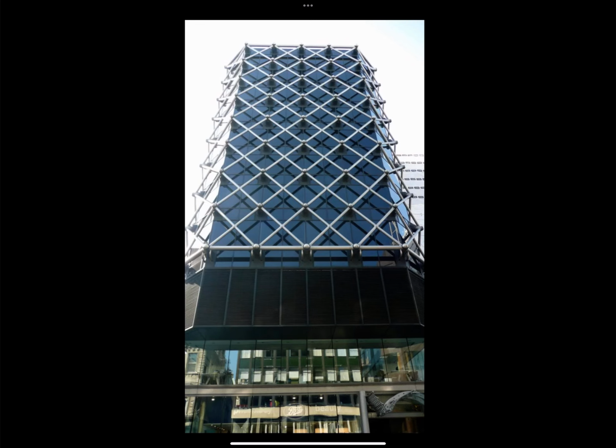So in this particular case, the exoskeleton is made of stainless steel tubes, which are filled with water with antifreeze in it. So the water keeps the tubes cool in the event of fire. So water-filled structures are very unusual. They're quite expensive to build. You would have to use stainless steel so that the steel doesn't corrode away.